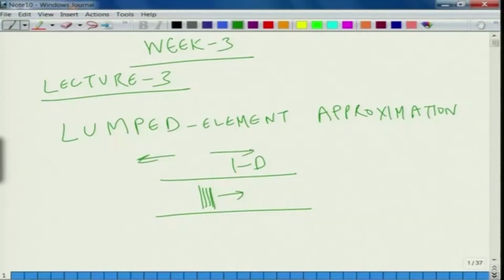So, what I am trying to say by means of this figure is that there are air molecules everywhere. There is an entire continuum, that is what we are assuming, and these air molecules are oscillating about their mean positions. If there is flow, they are also convected. So, because of this continuum of air molecules, we are considering wave propagation in a system with almost infinite degrees of freedom. Although it is a one dimensional system, it has infinite degrees of freedom.